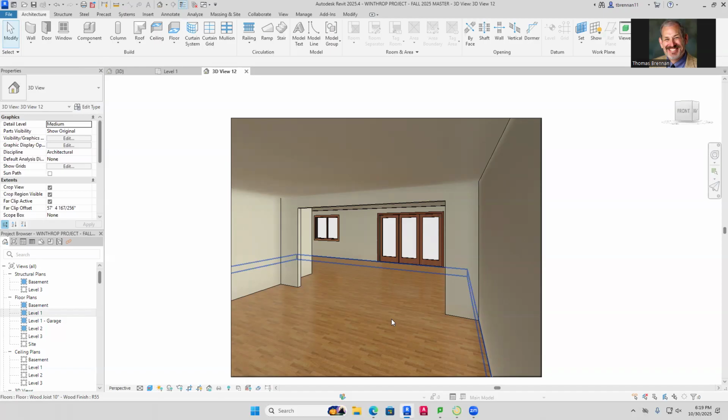And so actually the lateral elements that go across right here, those are going to be beams. But in a house, you're not going to put steel in it. You will see steel sometimes, like our basement, it's all wood, but it's got a steel beam that goes across that holds the middle part. But this particular house was all wood. We'll get into that later. But that's what you call this right here. This is a micro lam beam right up here, and that's what affords you support to span that margin of space.